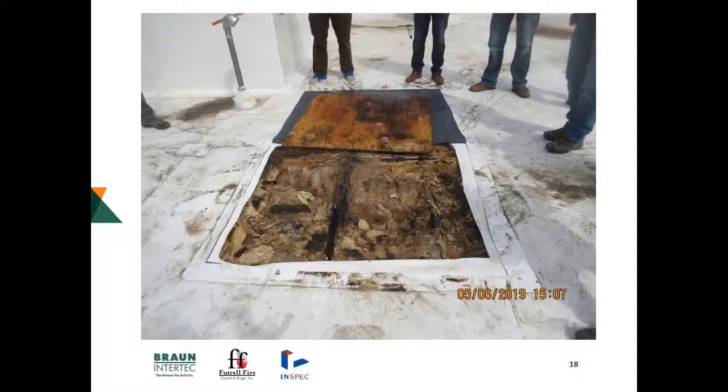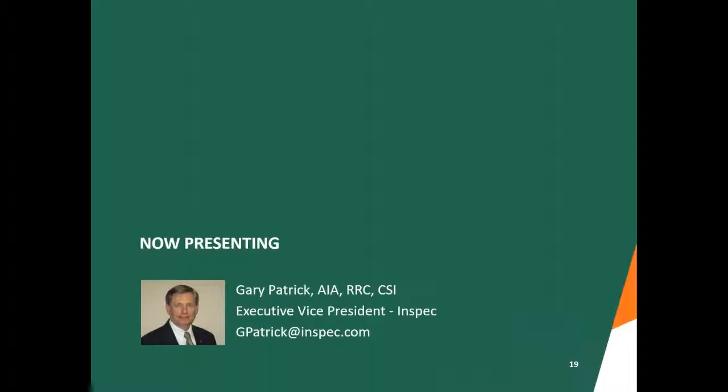The piece of plywood that you see there was not what was there a year ago in October when it was opened. That plywood was added, and by May of this year, so October to May, that piece of plywood has gotten mold on it, and it is thoroughly saturated with the air that's been bypassing into the attic.